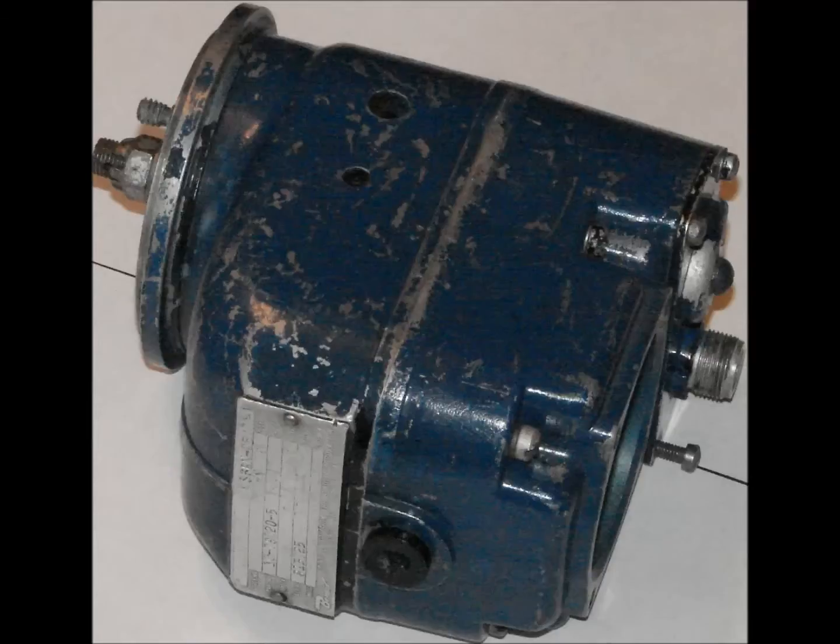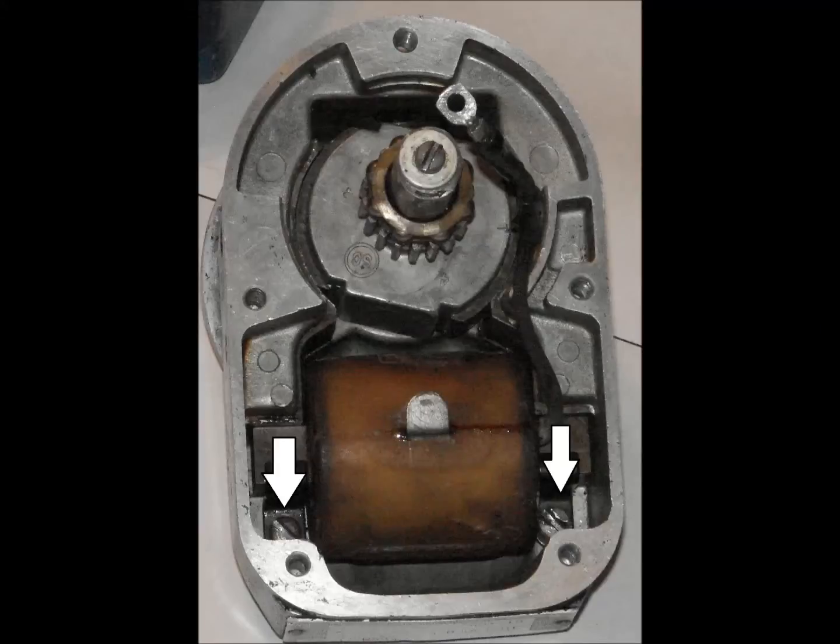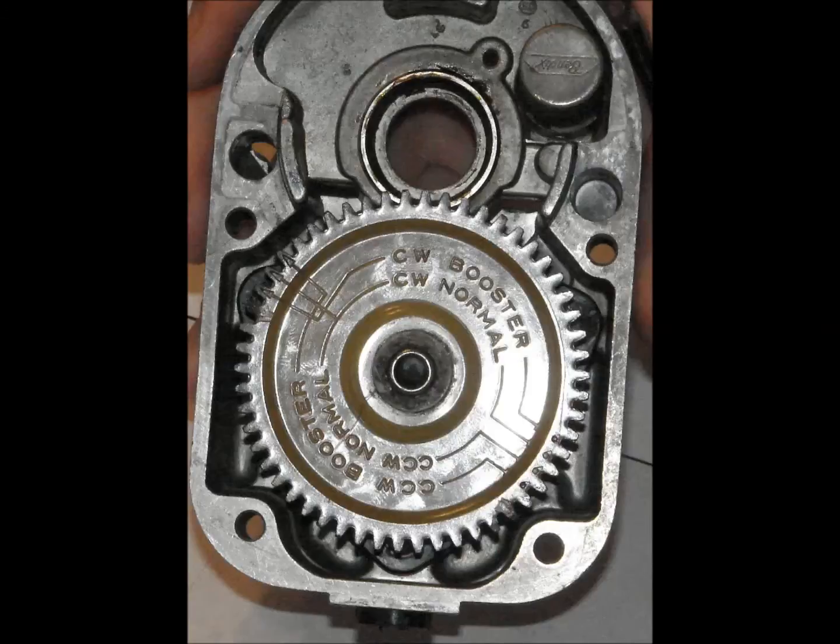of the critical components. The magneto case is separated in two halves, the magneto housing and the distributor housing. The magneto housing is the larger half and contains the coil, while the distributor housing is the smaller half and contains the distributor block along with the points and capacitor. The points cover is a small cover that protects the points, capacitor, and cam from FOD.